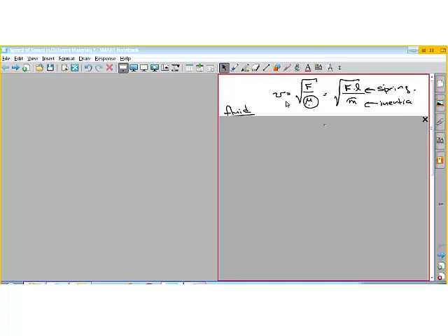And relating it to a spring mass system, mu is mass per unit length, so if I substitute that in there, I get this. And so the top gives you a measure of the tension times the length, kind of like a spring number. This is newtons times meters, which is actually newtons per meter for a spring constant. But the numerator is some kind of an elasticity term, and the denominator is an inertia term.